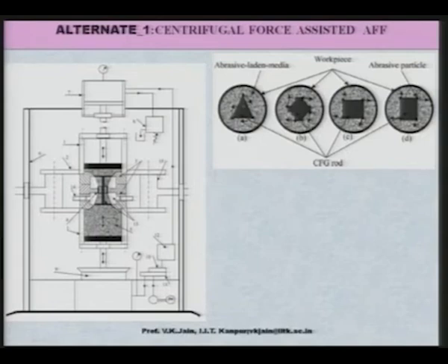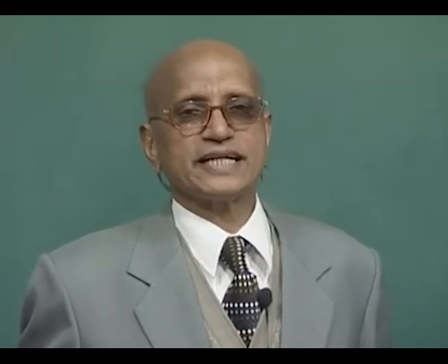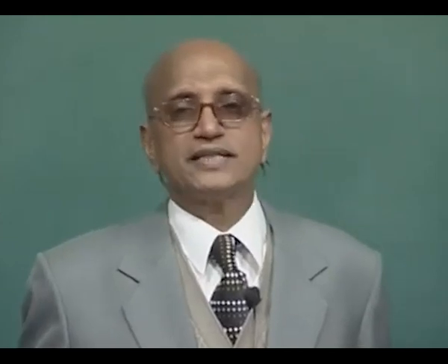Because of the rotation of this rod they assumed that centrifugal force is acting on the abrasive particle, and because of this centrifugal force the abrasive particle will penetrate deeper inside the workpiece, and if it penetrates deeper inside the workpiece and the cutting force is large enough to remove that amount of material from the workpiece, then the finishing rate will definitely increase.